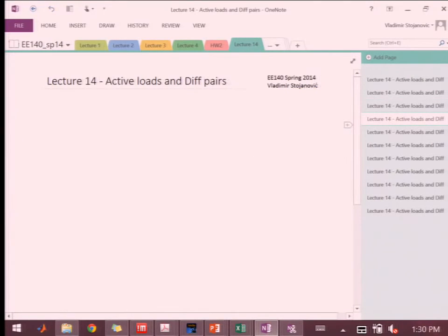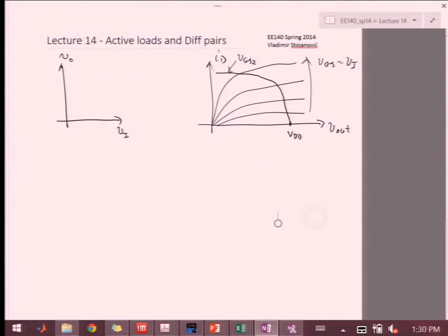And that will essentially determine what is this curve that I'm drawing. So this point over here would be my IREF or ID. Let's call it ID. Because I may have a multiplication ratio in the current mirror or something. But it's essentially the current that is set by I2.